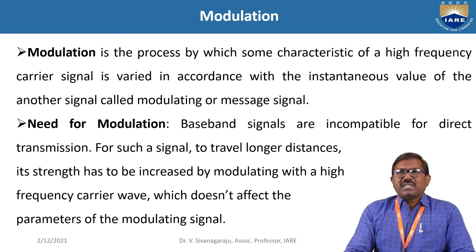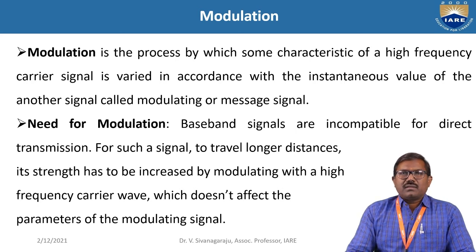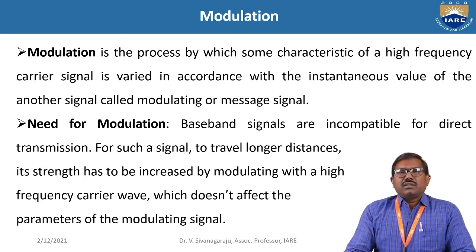So first, what is the need of modulation? Why are we doing modulation? We already discussed baseband signals. The message we can simply call a baseband signal, that means the original signal. For example, someone is talking. What is the frequency of the voice signal? It must be in kilohertz. So this signal cannot be transmitted over long distances. We are going to modulate the signal and then transmit.